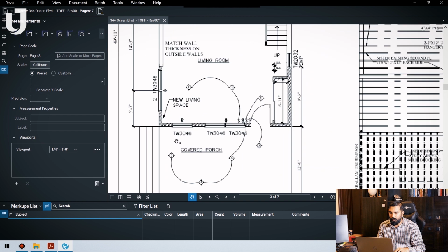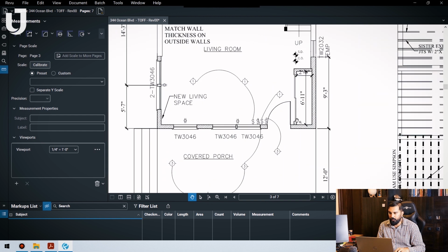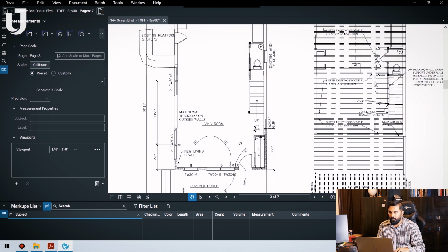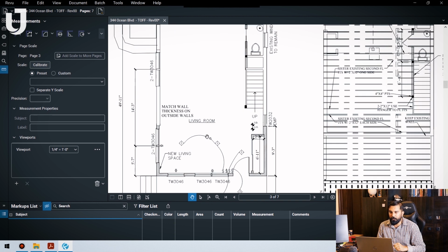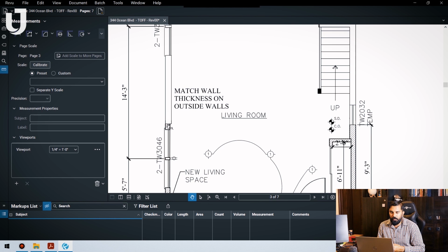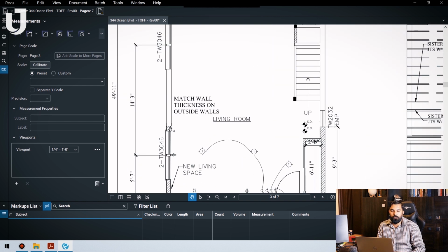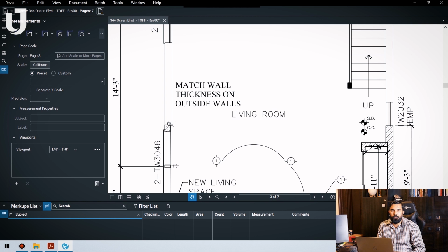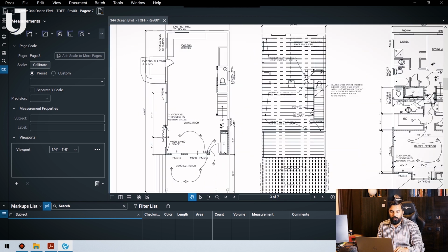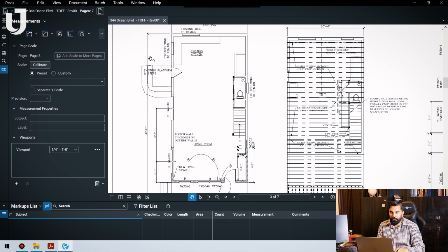On the first floor, the hatch pattern walls are the newly added walls. We should be conscious about the joint between existing and new wall. Sometimes most of the estimators miss this part, where we have to do the patchwork on the areas where existing and new walls are joined. Most estimators make this mistake of skipping this part.